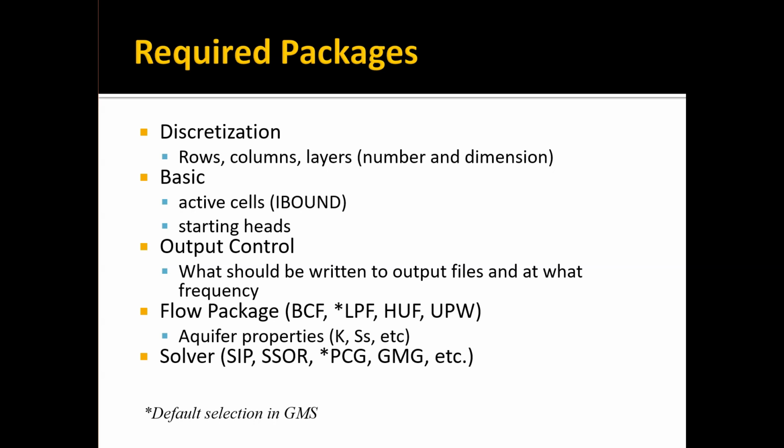And these are basically different algorithms for solving the equations that are formulated using your inputs and your boundary conditions. It comes up with this giant set of linear equations that then have to be solved. And each of these different packages uses a little bit different algorithm. Why do we need multiple solvers? Well, some are faster than others, but sometimes you'll encounter a problem where a solver just fails and it can't find a solution, so you pick a different solver, and a lot of times it works great. So there are good reasons to have multiple solvers.